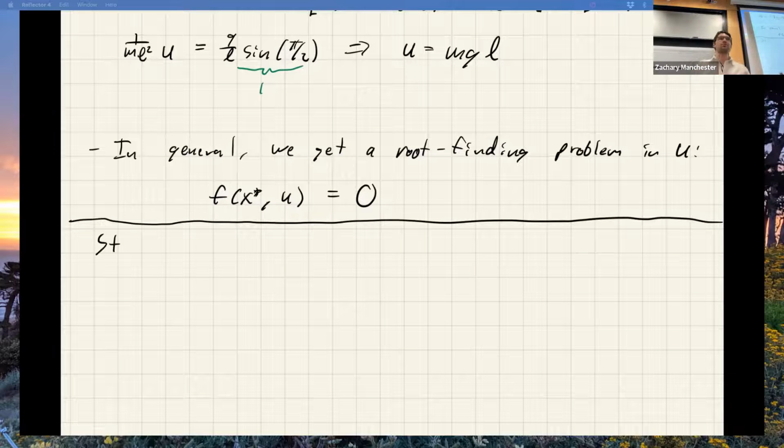This is bread and butter control stuff. Usually when we talk about designing controllers, implicit in that is stabilizing the system. We're usually trying to stabilize an equilibrium point under disturbances that maybe originally was unstable. A good example is if I want a quad rotor to hover. Quad rotor hovering is unstable open loop.